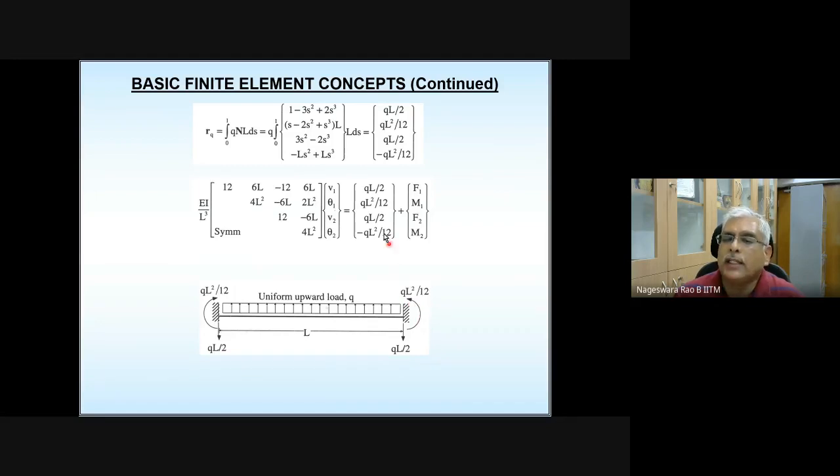So here, if you take a fixed beam of the same span as the length of that particular element that you are looking at, applied with uniformly distributed load, and try to find, from your structural analysis background, what are going to be the reactions at the support, the support forces and support moments.